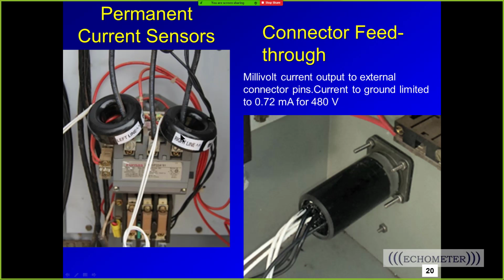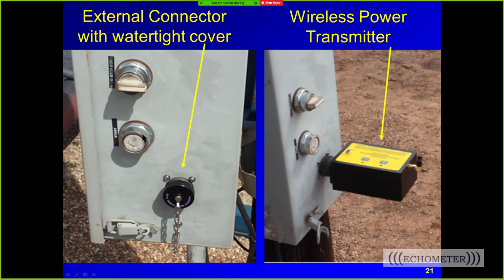The current still goes to 0 when you turn it off, so it doesn't really matter where the current sensors are attached. It matters more where the 3 voltage pickups are attached. They need to be on top of the HOA switch.